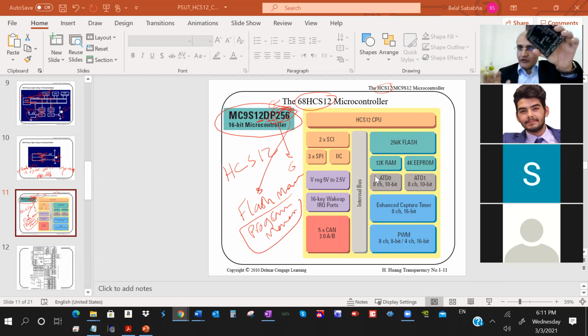Underneath is the CAN transceiver that just strengthens the signal. Okay, I can write code. When you end the class, you are going to be able to write code to write any CAN signal. And if you take these two lines, connect them to the two lines of your OBD connector, which connects them to the CAN network.